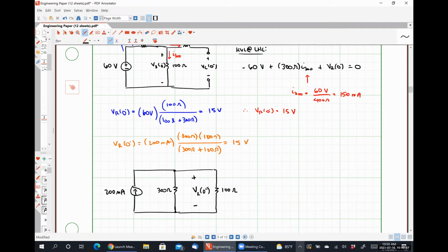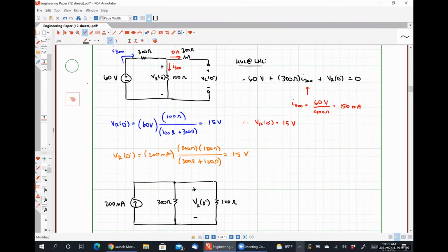So we've looked at multiple different ways that we could consider this circuit. And again, there's nothing wrong with doing the Kirchhoff voltage law that we did originally, recognizing that none of the current can split off and flow to the right, and then just writing that simple KVL loop around that left-hand side, substituting in the value of the current and then calculating that voltage.